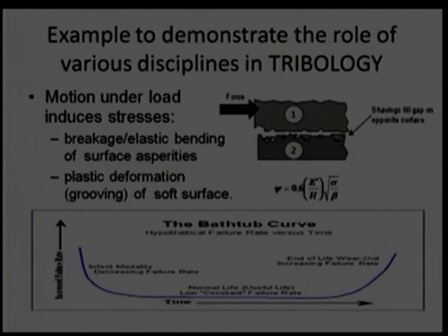It accounts for the Young's modulus of both surfaces as well as the Poisson ratio of the surfaces. The additional term is the square root of sigma divided by beta. Here sigma is the surface roughness of the component, while beta is the spacing between the two peaks.